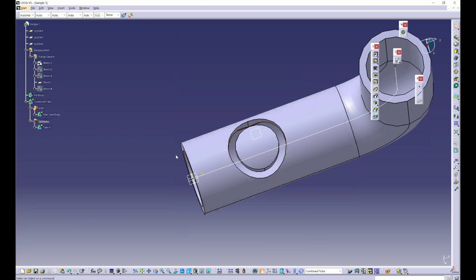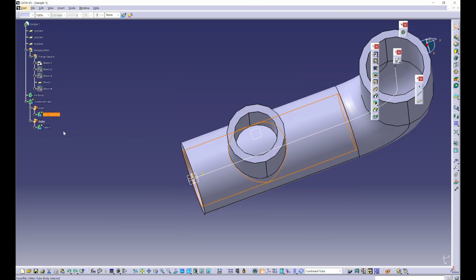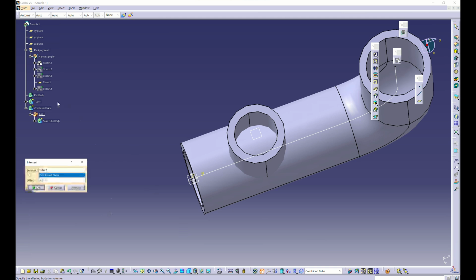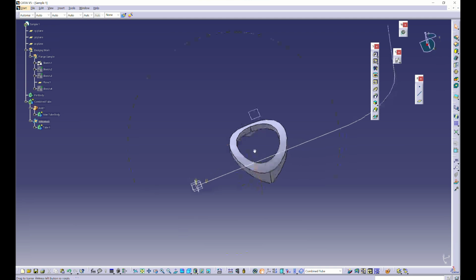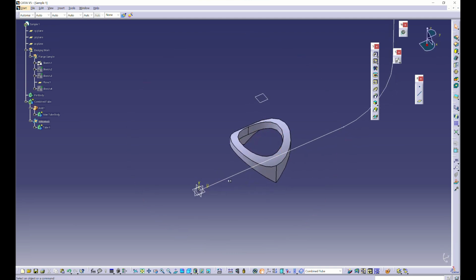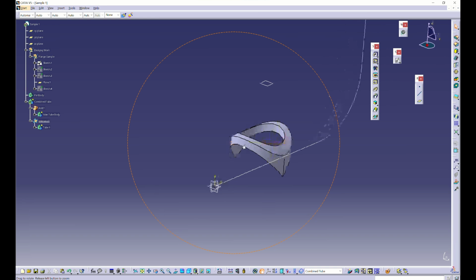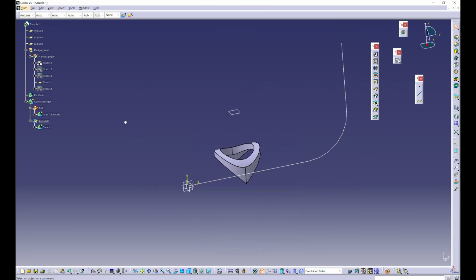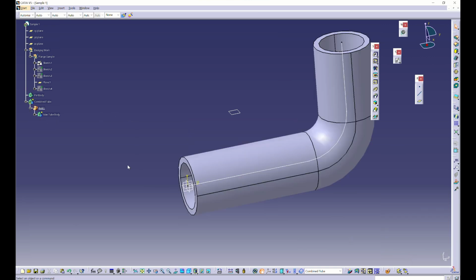Okay, so I will Control Z. Then if I use the intersect and add this to the combined tube, the intersected bodies will remain. The other bodies are gone or erased. So this is the Boolean operation function. Oh, it's gone. Control Z, Control Z.